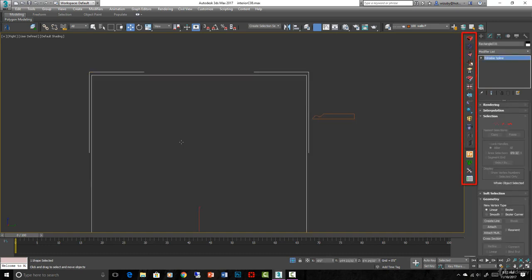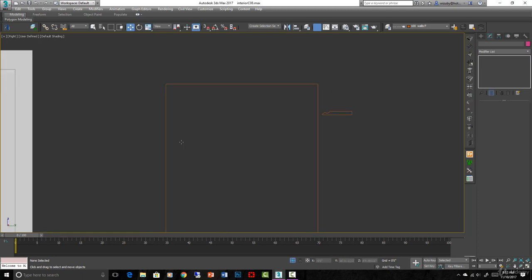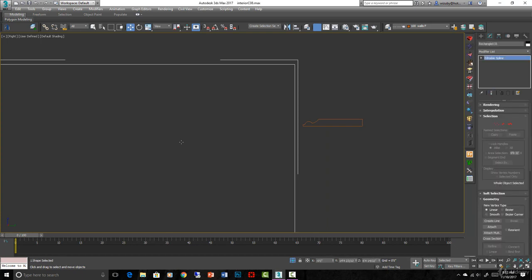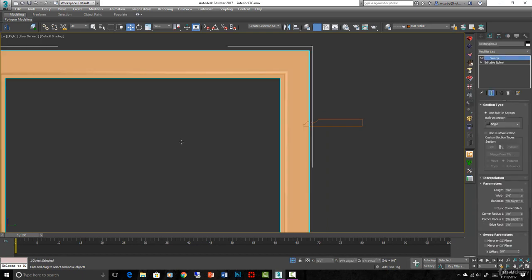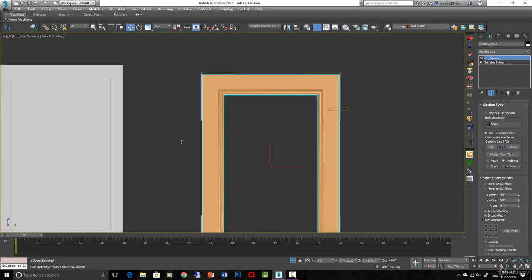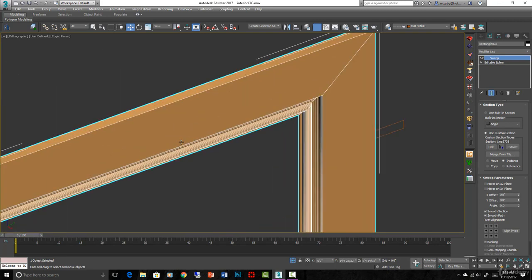I have the sweep modifier here, as you've maybe seen in some of my other courses, and if all this is too advanced for you, then you can go back to my other courses, which are more beginner. I expect some sort of knowledge from you from either previous courses or just from your own knowledge of how to model and all the things that I'm doing. So I'm moving through this pretty quickly. Take the edit spline, and you can use sweep right there and use a custom shape. Pick this one we just made, like so. Make sure everything's working right.